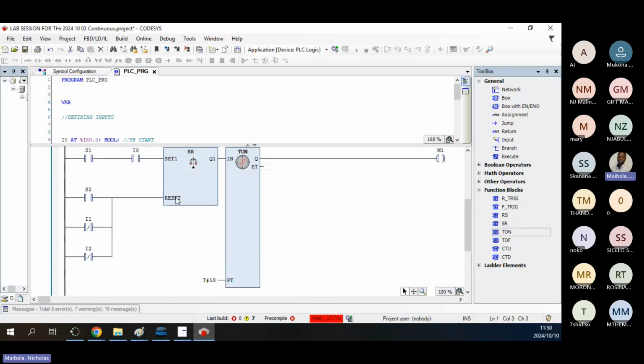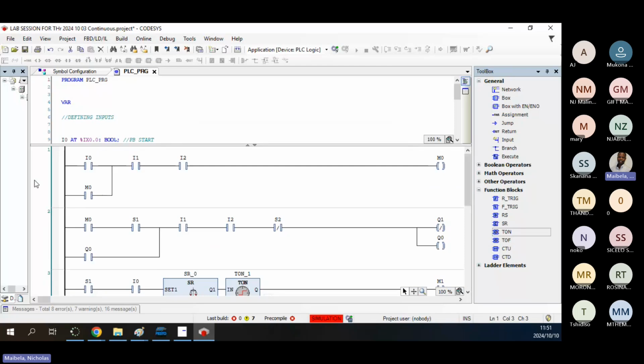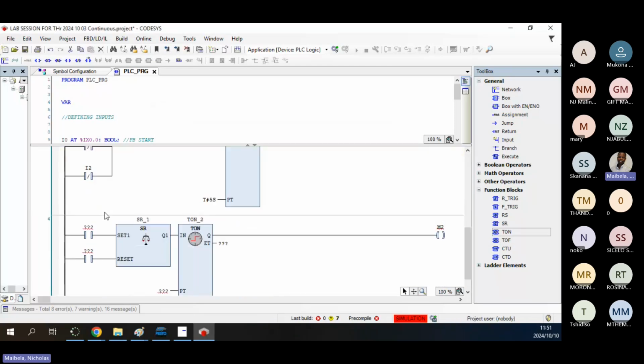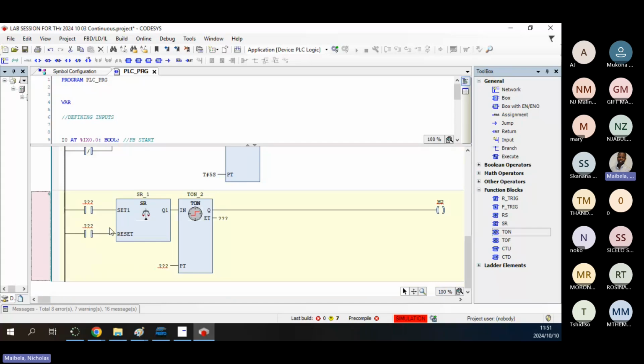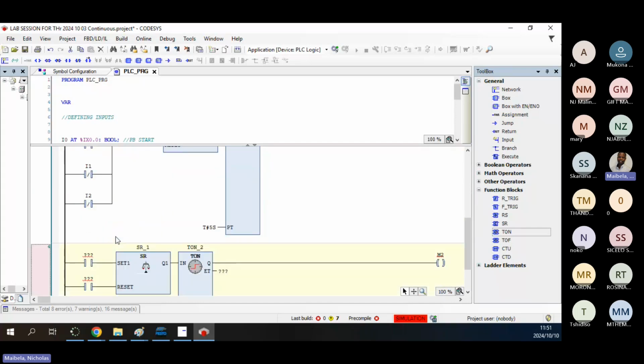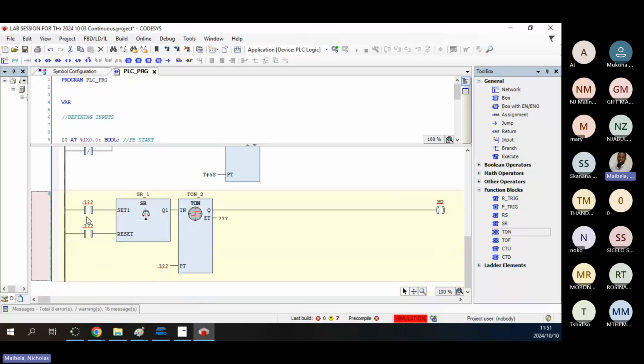So remember here on the timer, guys, we're not doing anything new here on circuit 3, this one that I've highlighted. It's just that circuit for delaying advancement, right? Now we're just doing a circuit for delaying retraction, of which we did as well. Now we're combining the two, and the circuit will run continuously, but there'll be delay in advancement and there'll be delay in retraction, right? Okay, so here it's for retraction.